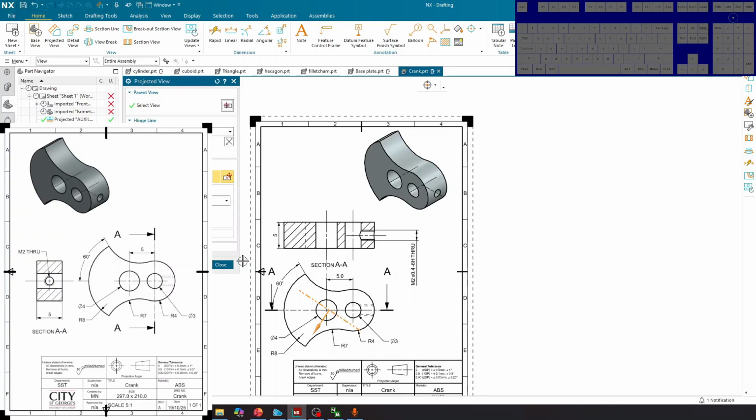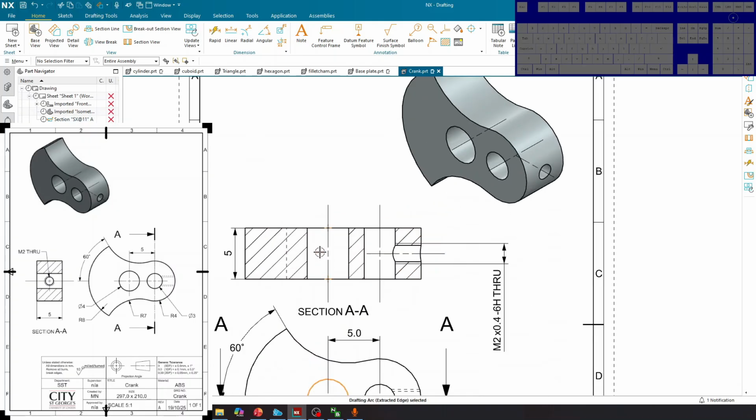Now, some of you guys may have noticed, but this engineering drawing over here is different to the previous engineering drawing that I used in the other video. Now, why is that? It's because I realized that the circle over here in the other sketch, the depth of it, how far it goes into the material, wasn't fully described. You can't tell. It doesn't describe it, okay? And so for this drawing over here, I've instead shown clearly over here that this hole goes all the way through.